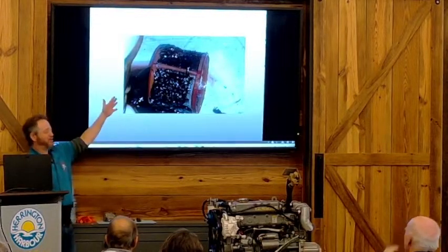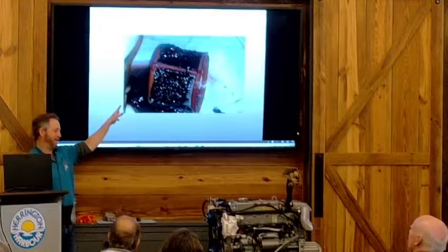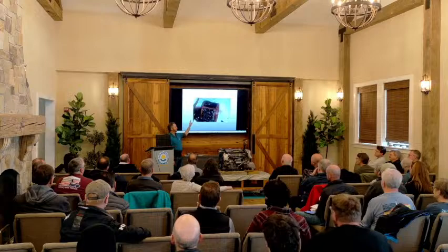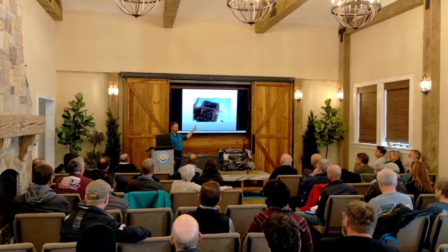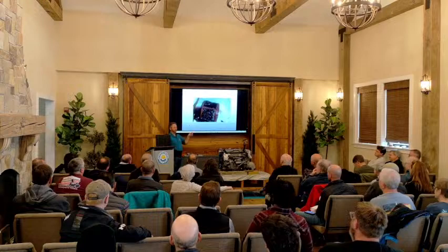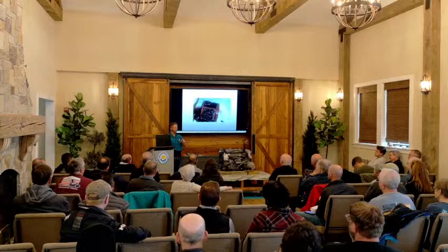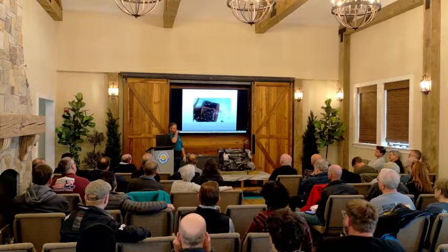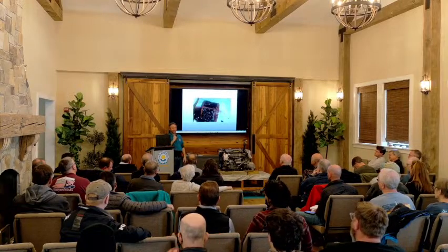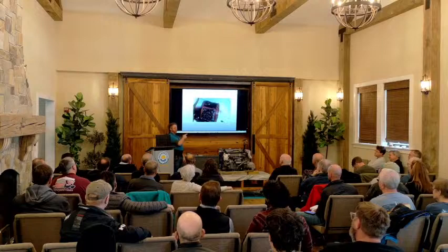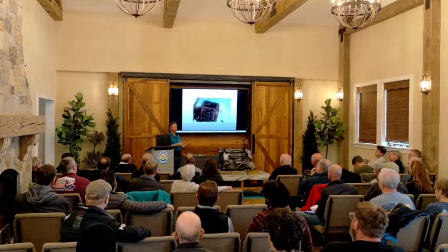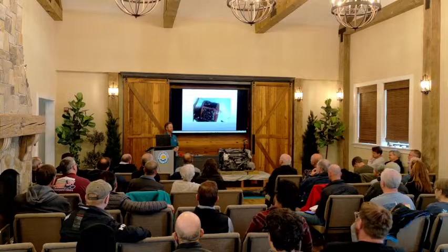Well, see, there is a type of boat brand that uses universal engines, and every boat they built, they installed this electric pump in the wrong location. So they put this pump before the Racor, so this screen is doing the brunt of the filtering. Now, I'm one mechanic, and I know I've done over 80 boats in my career for this company. Not for them, but fixing their mistake.